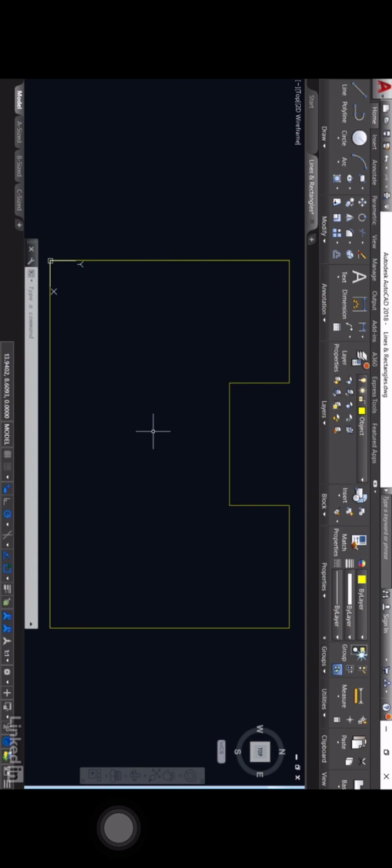The quickest way to type in coordinates when you're using AutoCAD is to literally type them as coordinates. So 5, 4, 10, 7. You can also use negative values, which purely define the direction of the line from one point to another. So I'm going to draw some rectangles now, which you can follow my lead on as well.